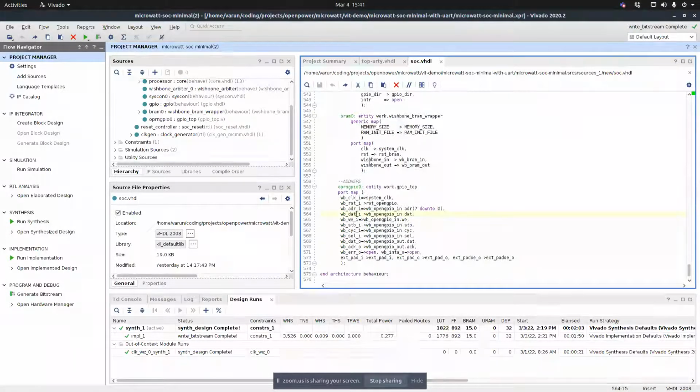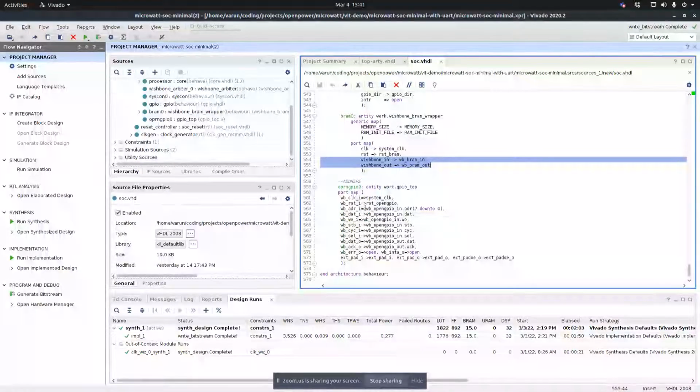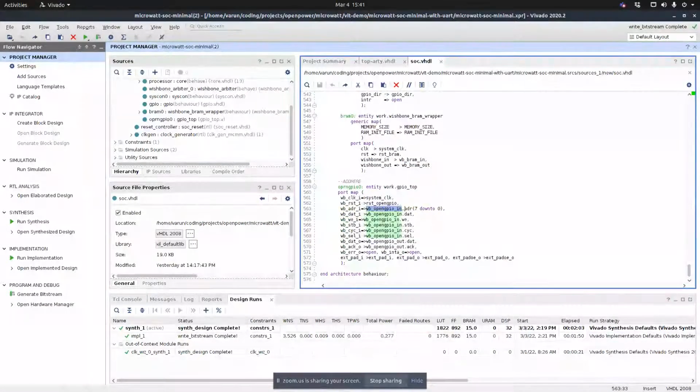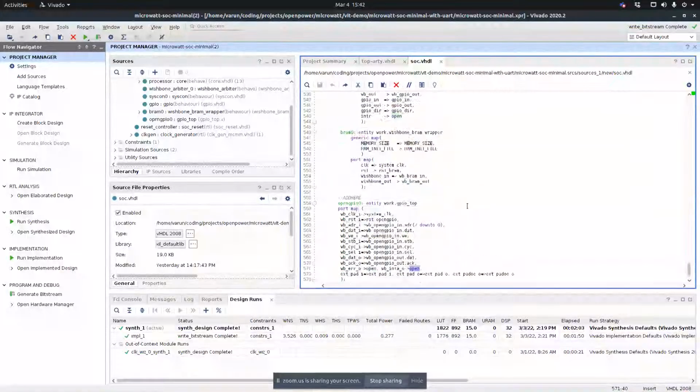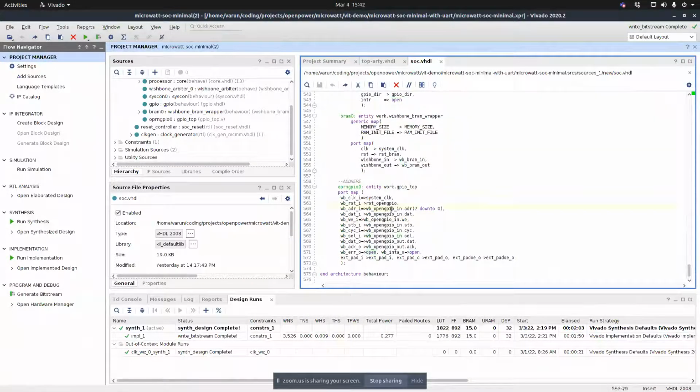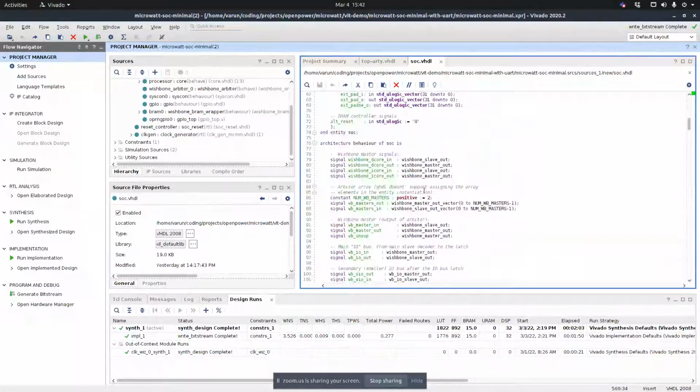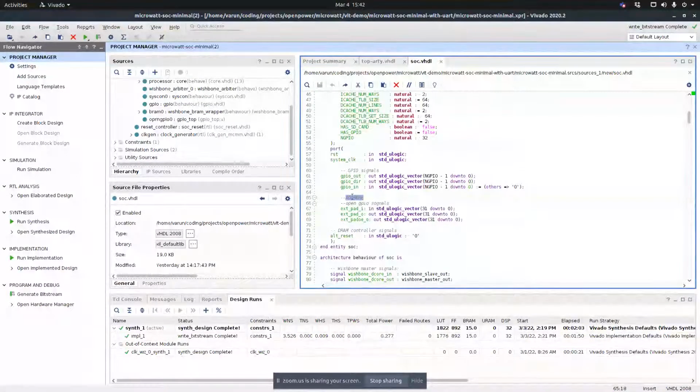And so when you're connecting, you cannot simply do this. It could have been much easier, but you have to individually wire, like the Wishbone address to the GPIO address, like that. And any external signals that your GPIO is using, you have to wire that as well. Some you might not be connecting, you can declare them as open, etc. So these two signals, GPIO in and GPIO out, you have to define. Okay, let's go one by one.